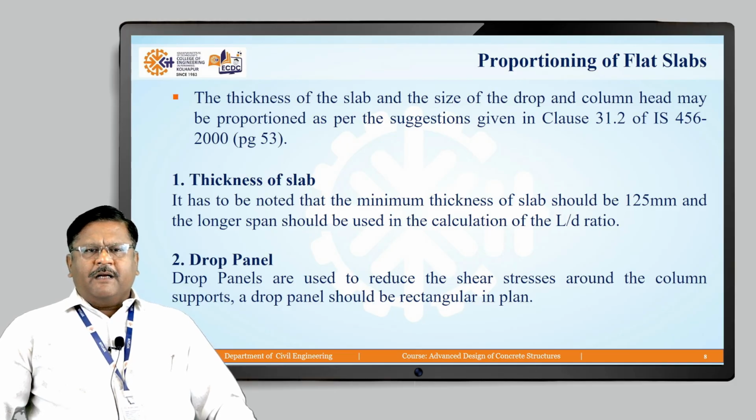Second is drop panel. Drop panels are used to reduce the shear stresses around the column support. A drop panel should be rectangular in plan. Now, how to calculate the depth of drop panel and so on, we will discuss at the time of problem solution or design procedure.